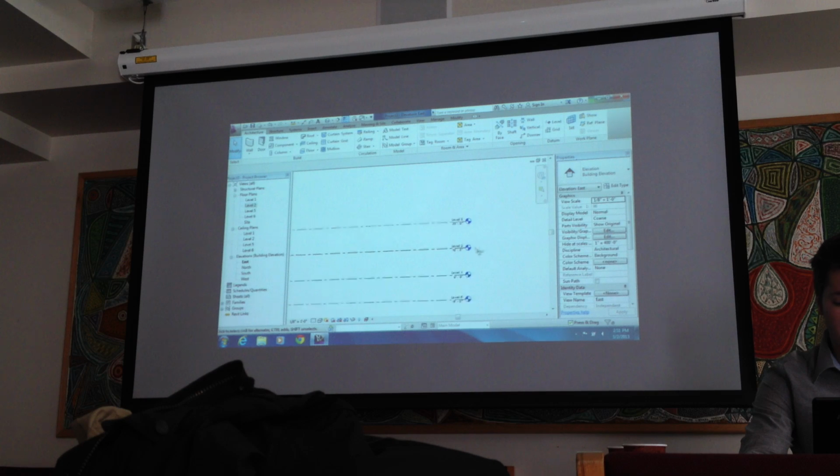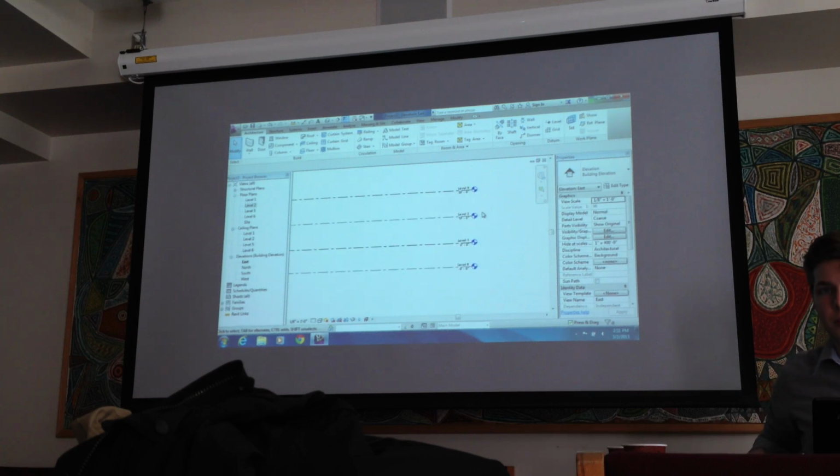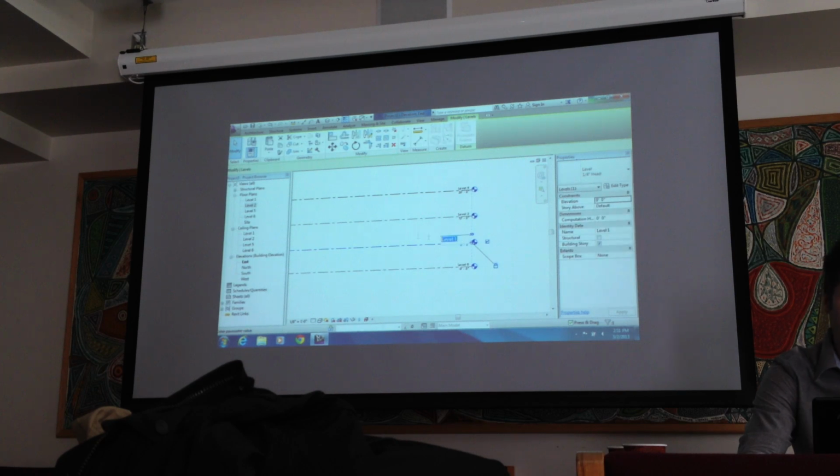The way Revit works, it automatically names the floors when you create them. It tries to be a smart system, although it can screw up, obviously, like see above. Since I was creating ones before and deleted them, it goes level 2 to level 5. If you just click them initially and place it, it will work that way. Also when you change one number, say the very first one, all the other ones should follow.